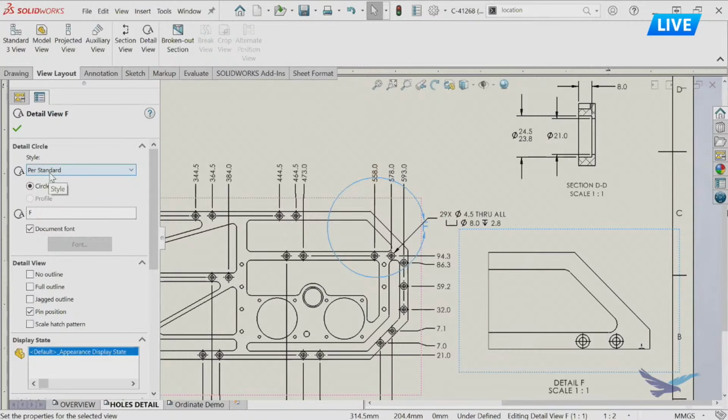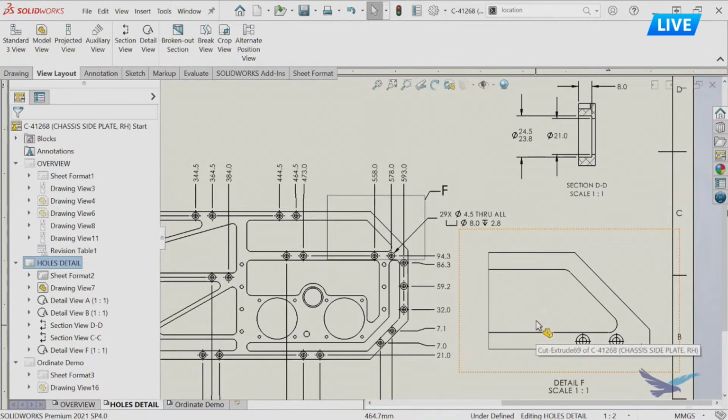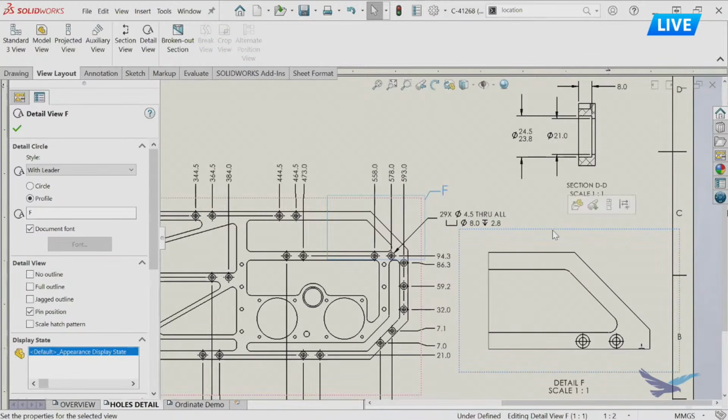And this can explain a lot of strange behavior that you see in drawings if you're trying to do a foreshortened dimension, or trying to adjust your extension lines. You might feel like, hey, SOLIDWORKS is just blocking me from doing what I want. It may be because of your drafting standard that's selected. So you'd either want to go and change the settings in your template if you're going to be using a modified standard. Like a lot of our users aren't using pure ANSI or ISO, they're using some modified standard, or just locally override it, and then that'll allow me to choose the type of display that I want here. Ryan, another vote for that. We see that often in tech support, where the standards are just preventing a user from doing what they want. So if you do face that, you might take a look at modifying that standard.